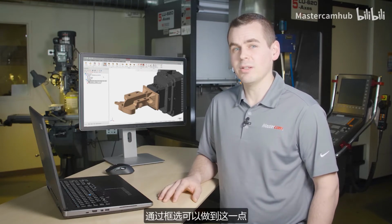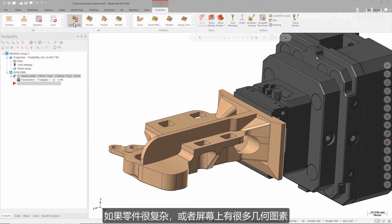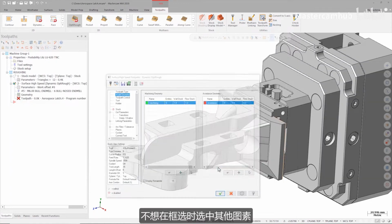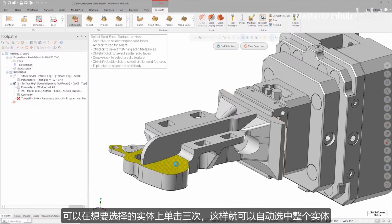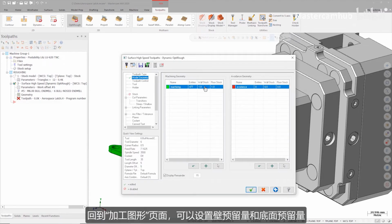I could do this by window selecting, but there's another method available in Mastercam. If the part is complex, or there's a lot of geometry on screen that I don't want to accidentally pick when window selecting, I can simply click 3 times on the solid body I want to pick, and the entire body is automatically selected. Back on the machining geometry page, I'm going to enter stock to leave values for my walls and floor.